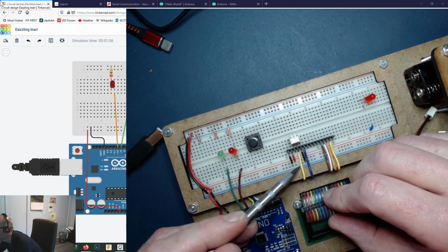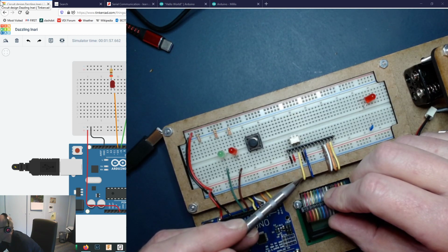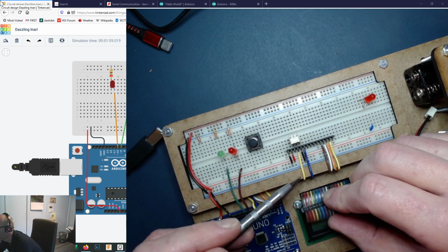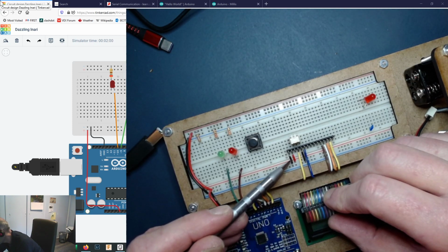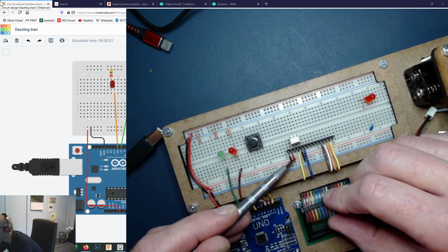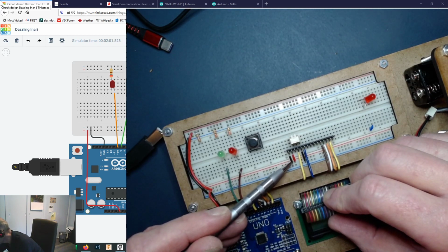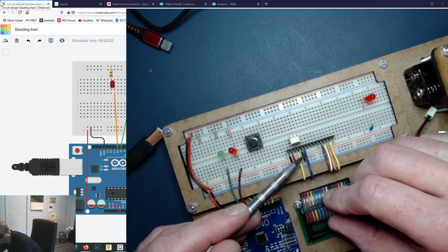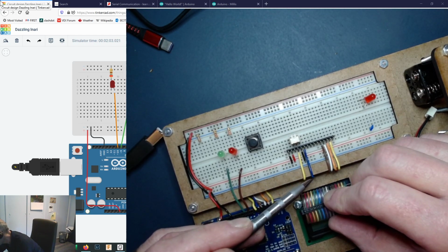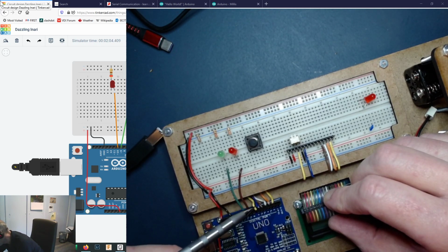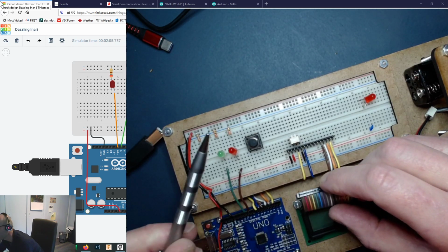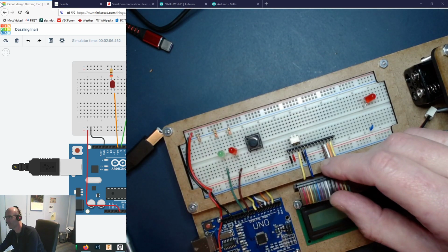It's really important when you do breadboarding that you start getting used to keeping your wiring nice and neat and tidy, because when you start to get multiple wires, it can be a nightmare to troubleshoot. So if you use different colors for different signals and always do black for ground and always do red for your +5 lines, then you're going to be able to tell by looking at a wire not only what it is, whether it's ground or +5, but you can also tell where it goes just by saying, hey, look at that blue wire. It goes down underneath here. I lose track of it, but it comes out on this side, and there's a blue wire going right into pin 6. So we're going to hook this up just like we did on the computer.